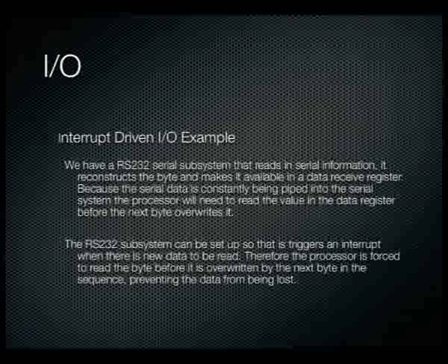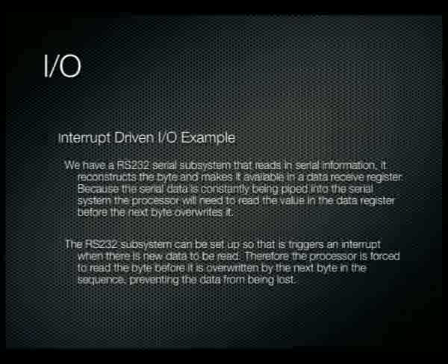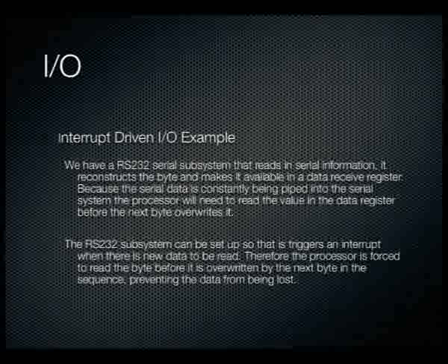If the processor wasn't equipped with interrupts, the data would simply arrive. If it didn't read it within those 8 clock cycles, it'd be overwritten, so we'd end up losing data. If the processor was trying to dictate when data moved around, it would end up losing data because it would be unaware that new data arrived in the serial port, wouldn't grab it in time.